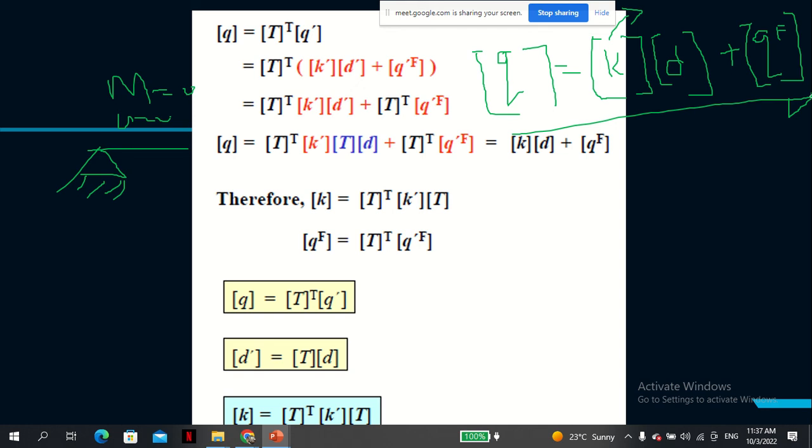So first of all you need to know what the boundary condition says, and what you know. Now this part is also important. If for example you have loads applied at the nodes, for example here, it might be useful. So if you have a load applied directly at the node here, then you put it here. You have to add it here. Now these Q are the reactions, for example, the VA here and the moment.